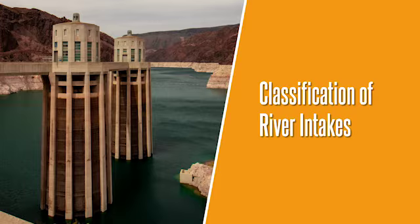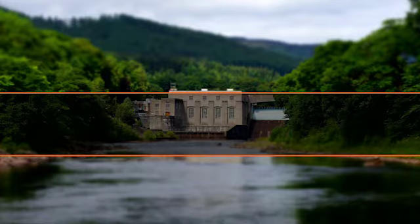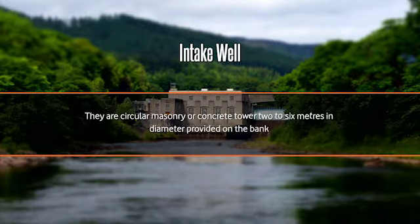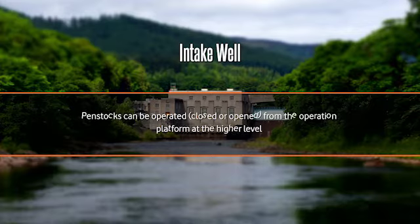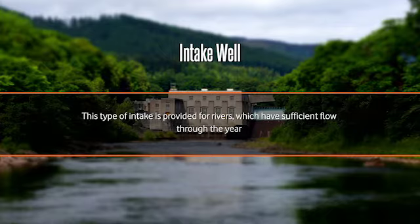Now the classification of river intakes. Intake well. They are circular masonry or concrete towers, 2 to 6 meters in diameter, provided on the bank. The water flows into the intake well through the penstocks located at different levels. Penstocks can be operated from the operation platform at the higher level. This type of intake is provided for rivers which have sufficient flow throughout the year.